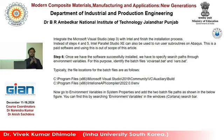When you install all things, Microsoft Visual Studio, Intel compiler, you need to make sure that your environmental variable has that kind of readability, this one and this one. Either you can add those file directories by the environmental edit setting. Okay, when you add this directory, you will make sure this will be in the system. Now go to the system environment and edit the path as shown below. You can find system environment in the Windows search bar. So you can make sure that these things will be in your environmental variable path, right? Like this. See, those paths we have included.